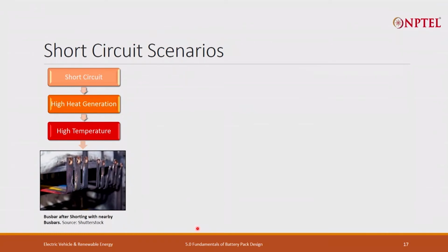First your insulation will melt, because generally that is made of some types of plastics or rubbers, whose melting temperatures are quite low. Then the local melting will start happening, which you can see here in this picture, especially here. Once local melting started happening, after some time that part will fail completely.